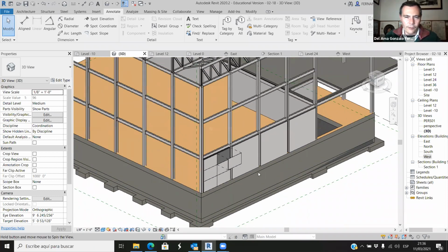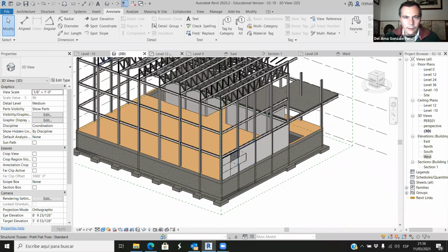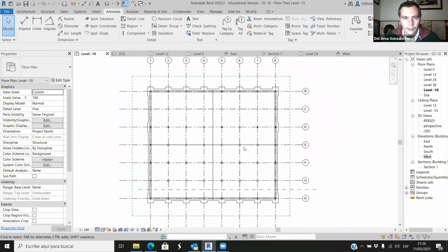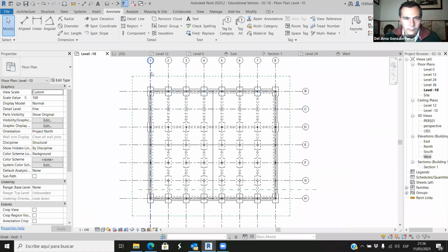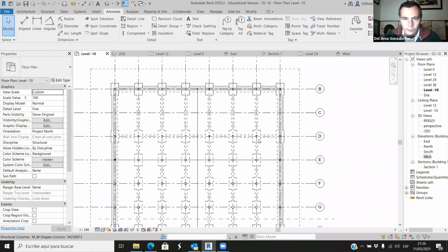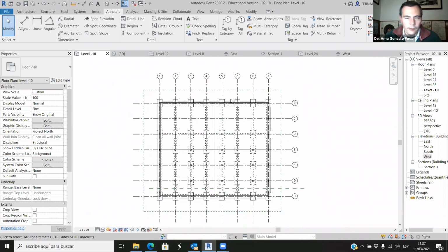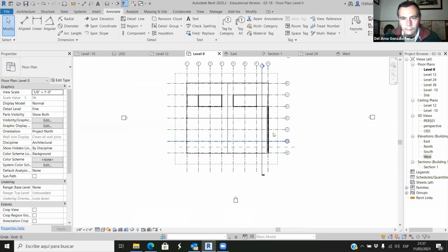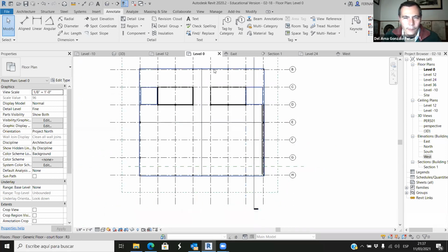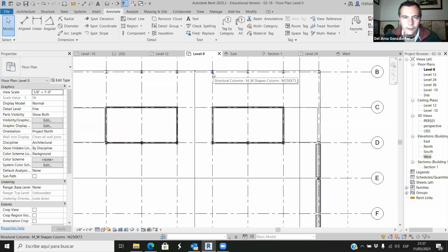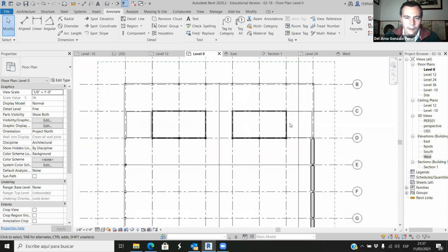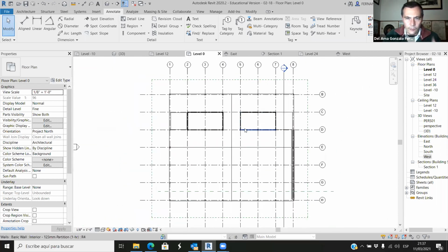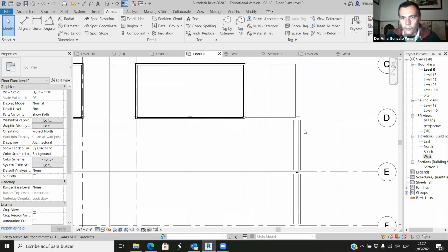This is what we are going to do. But first, we need to make sure that we have a feasible structure. We have grids, we have columns, we have footings, we have retaining walls. So this looks like a building. Then if we are working with steel structures, creating grids and having symmetry is something good, because there are a lot of decisions that are already made because of the grid and because of the symmetry.